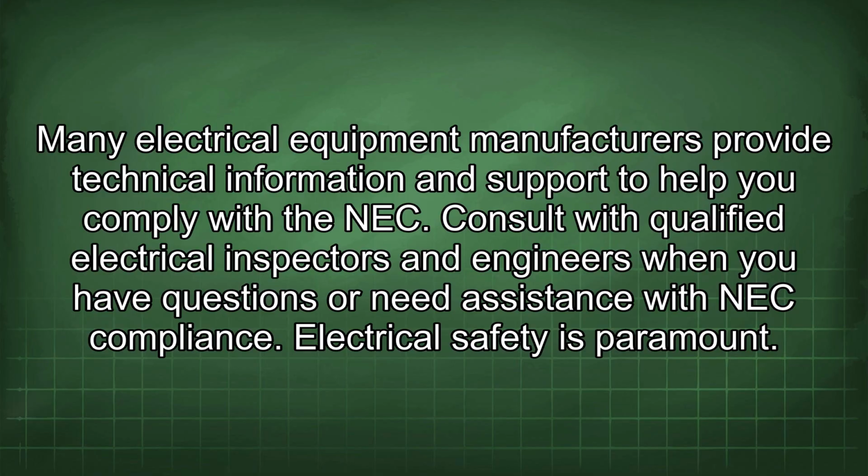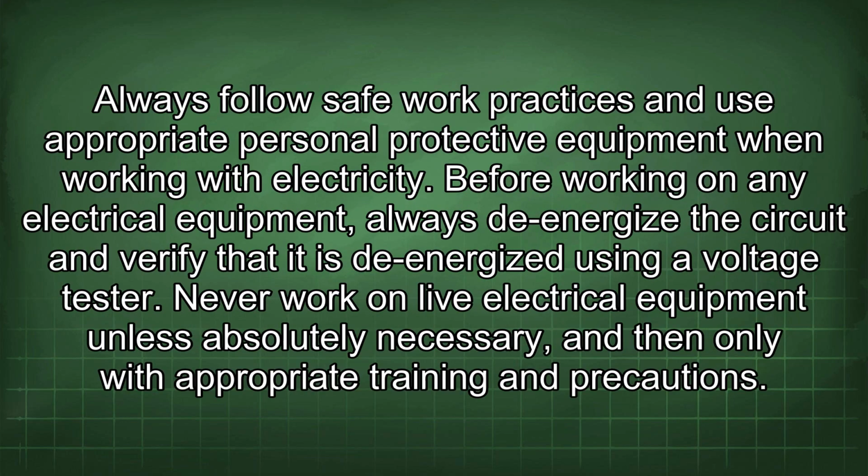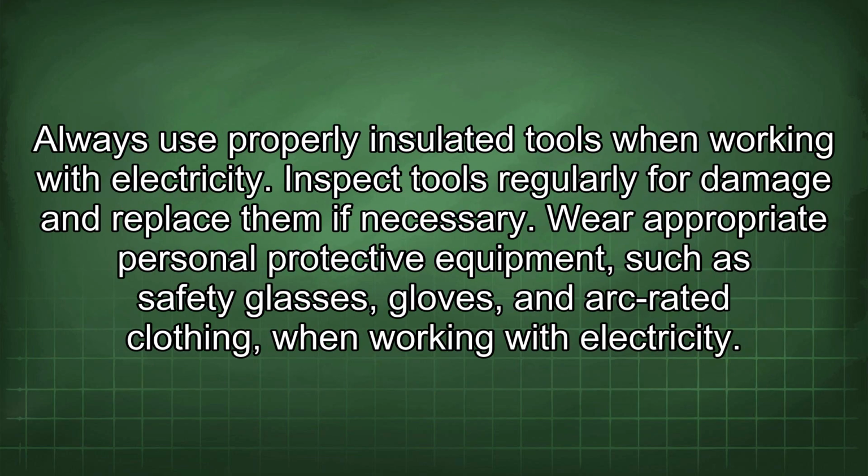Electrical safety is paramount. Always follow safe work practices and use appropriate personal protective equipment when working with electricity. Before working on any electrical equipment, always de-energize the circuit and verify that it is de-energized using a voltage tester. Never work on live electrical equipment unless absolutely necessary, and then only with appropriate training and precautions. Always use properly insulated tools when working with electricity. Inspect tools regularly for damage and replace them if necessary.